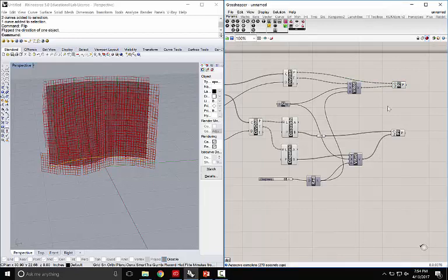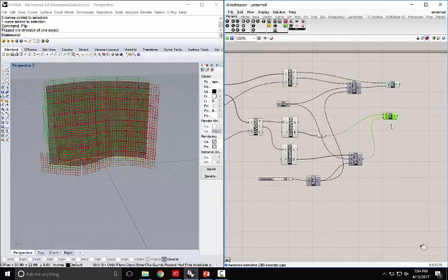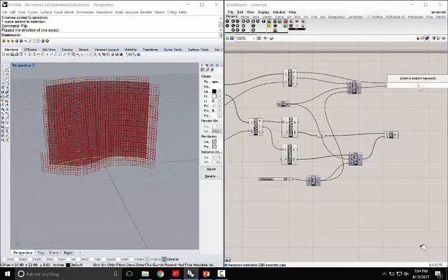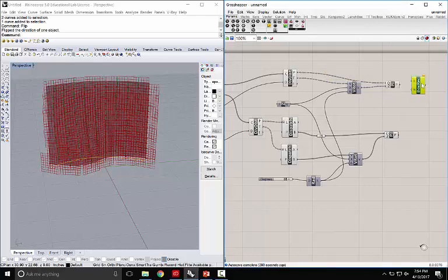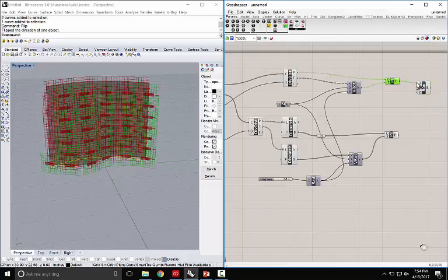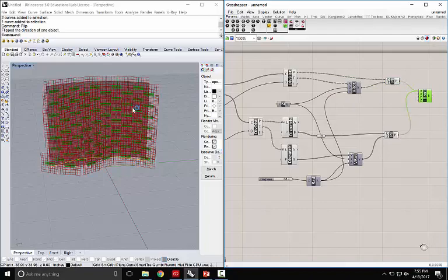All right. So I think that the X direction is going to be the width. That's correct. And the height should be the Z. That looks correct. And the width then should be the Y. That is not correct. Let's try that again. So maybe the Z. There we go. Those look correct. So we've got the width of the bricks going into the Z value and the height going into the X value. That's because our planes that we see here are actually rotated. They don't have a Z value going up. Instead, they have a Z value going towards us.